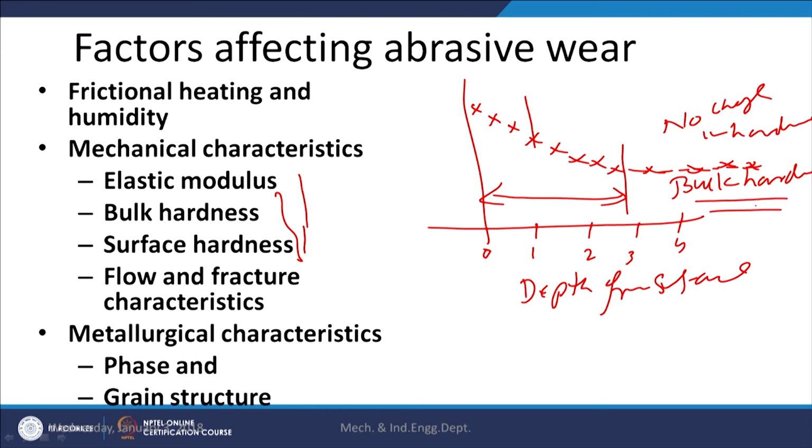What matters in abrasive wear, or in all forms of wear, are the actual surface properties, and these surface properties are actually modified during abrasion, adhesion or erosion. So, we are more concerned about the surface properties, which are usually higher due to the surface layer deformation under actual service conditions like abrasion, adhesion, etc.